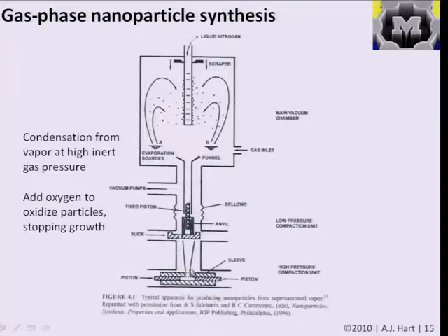So this is an effective apparatus where, by a general method of creating a vapor, understanding the nucleation of that vapor material and its deposition on the solid surface, you can create particles of a whole bunch of different types of materials, albeit it's a very low throughput apparatus, because you could imagine if you're just creating a few layers of these little particles on a cylinder, you don't get a lot of material at a time. So something that's a bulk method that takes advantage of a volume of a liquid or a volume of a very large reactor might be quite more scalable.